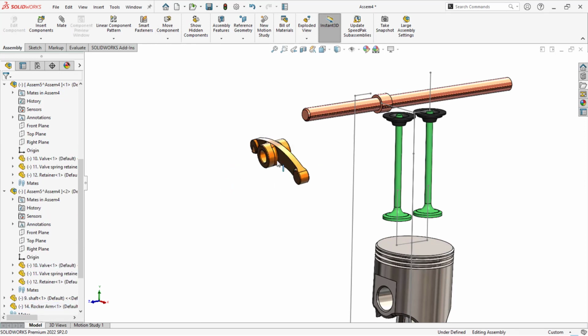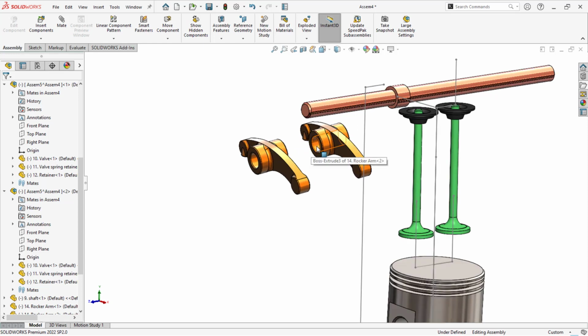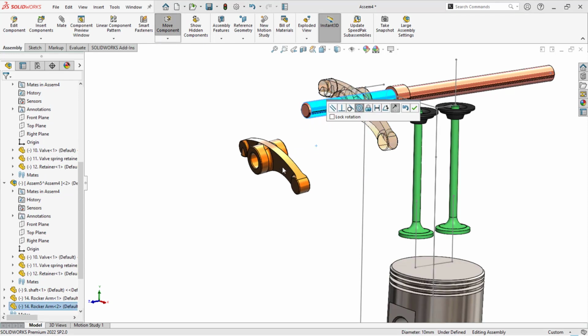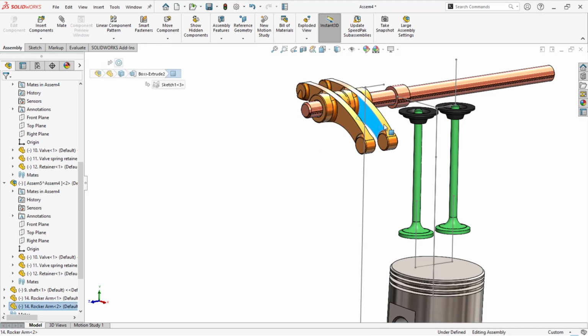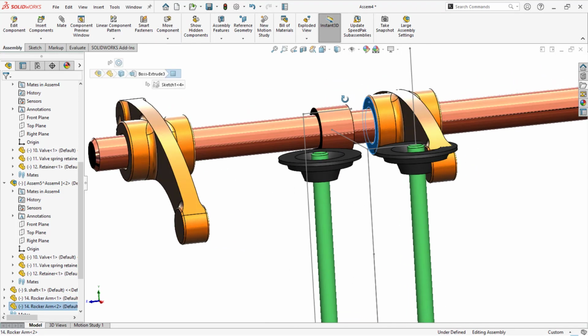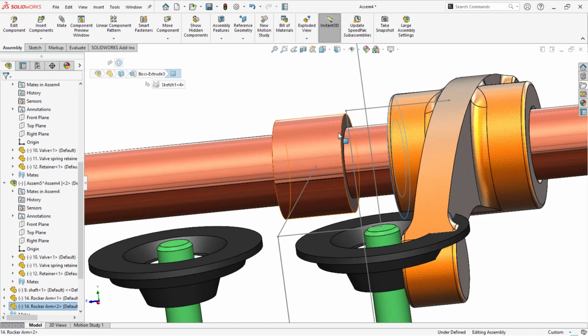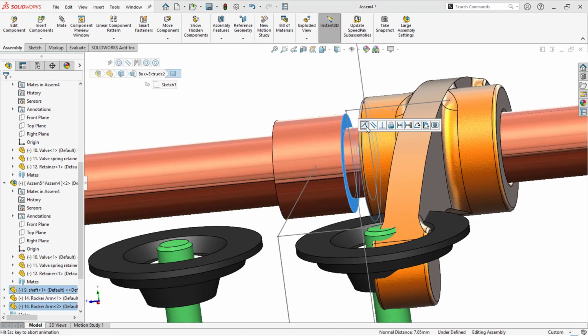I need to copy one more, hold the control, drag it out. Done. So concentric, just hold the alt, drag it. Same thing here. Okay, these are the two shortcuts. Whenever you want you can use it, holding the control or holding the alt, drag and drop, it depends. Whenever you feel that is okay, you can use it.